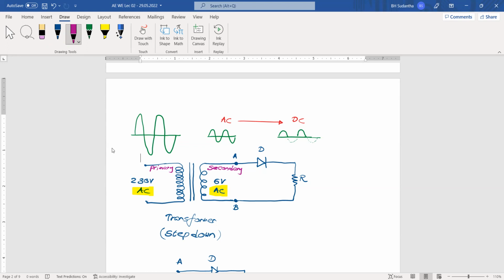After that, here we have this small AC waveform, which is the input waveform of our simple circuit. When you send this AC voltage through the diode, at the other side of the diode, on the resistor side, we have only the positive half cycles. Why? The positive half cycles can forward bias the diode, and then positive voltages can go to the other side of the diode.